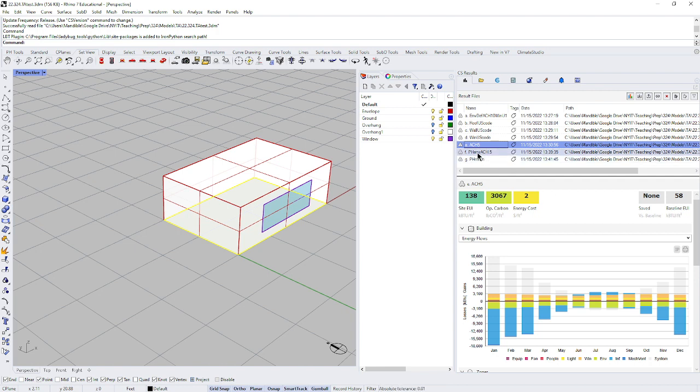Then what I did is I went to PH, which is for Passive House, which is sort of the gold standard for envelope design right now in the world, or at least it's pretty good. And so there's a certain level of insulation, air tightness, window performance. So I did all of those at once. I brought us to an envelope that has a passive house level of performance, including the windows, and I changed the ACH to 0.5 instead of 5, which is about what it would be for passive house.